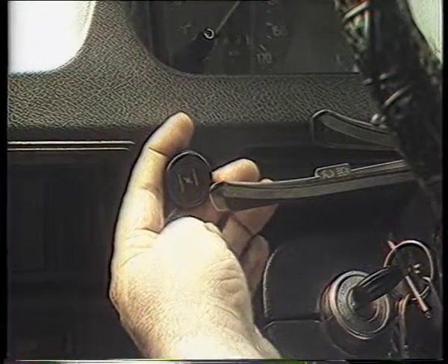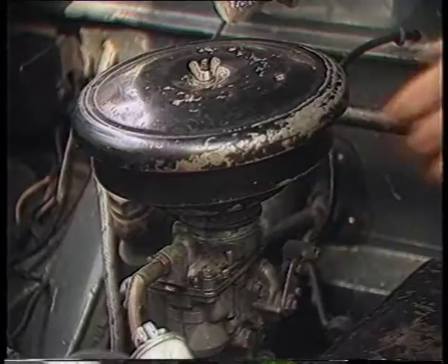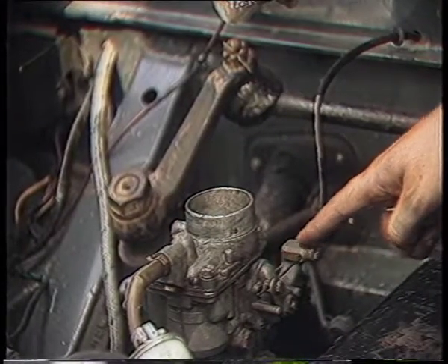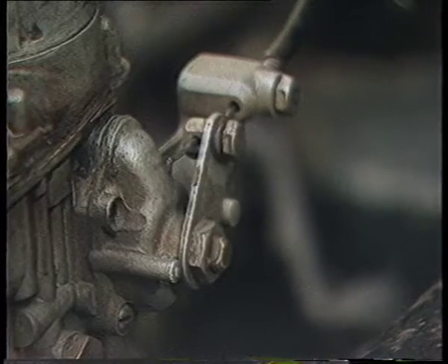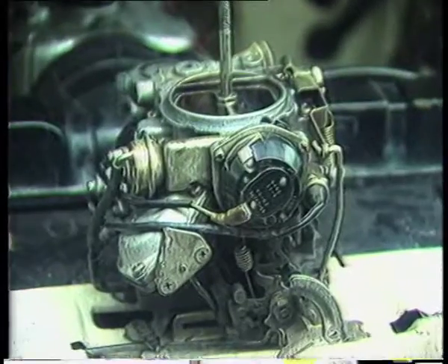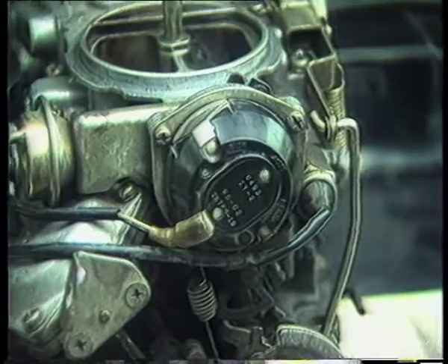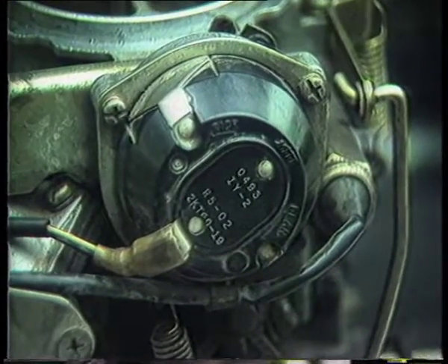Mechanically controlled chokes are operated by a pull rod on the dashboard. The pull rod is linked to the choke valve. When the rod is pulled out, the choke valve is closed. With this arrangement, the driver must remember to push the choke control knob back in the de-choked position after the vehicle starts. If he forgets or fails to do this, the mixture will be too rich for the engine's needs and the engine will overflow, and in the long run this will cause excessive carbonation of the valves, piston rings and spark plugs. Because drivers often forget to de-choke the engine, modern cars now have automatic choke mechanisms.